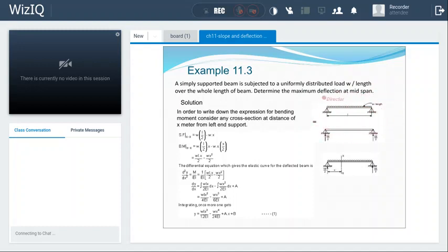If you want, you can join another class for shear force and bending moment, where we explain how to find the reactions for a simply supported beam when there are different types of load. But here it is a simple case. There is only uniformly distributed load for the entire span. So because of symmetric loading, the two reactions will be equal.